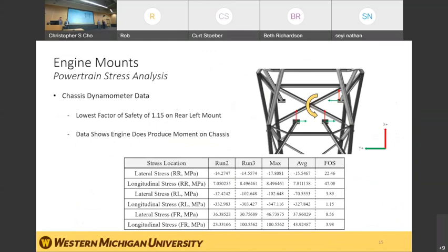I would say you could create individual custom engine mounts, but then in the event where one does fail, all the stress will then go onto the other ones, and it could actually cause all of them to fail. It's also much simpler to give them a standard size that they can all hit. I do agree that the front can differ from the rear, customized to be slightly thicker in the front, as most of the stress is seen in the rear.